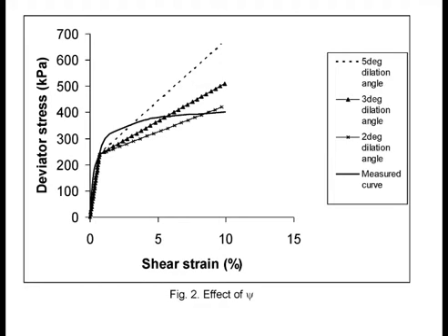So I used that. I didn't use this particular point from the stress strain curve. Now, I'm not saying that this point is wrong. It's just that I usually find that if you use the stress strain curve, it is very hard to define where the yielding occurs, because the curve turns around in quite a gentle way. So you could be using a point here, here.